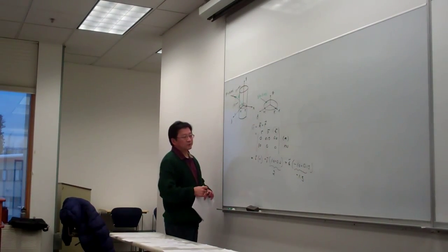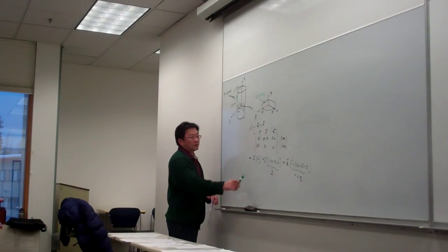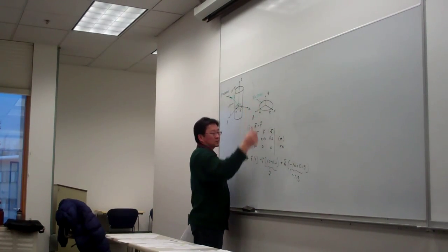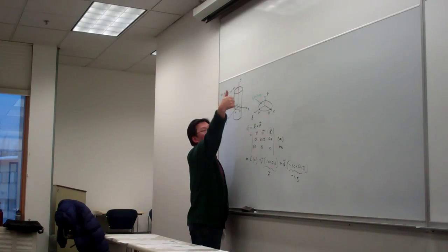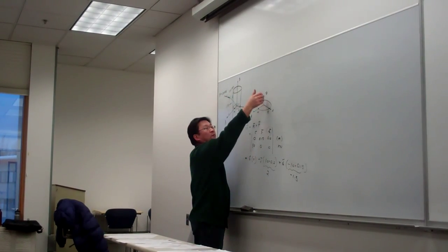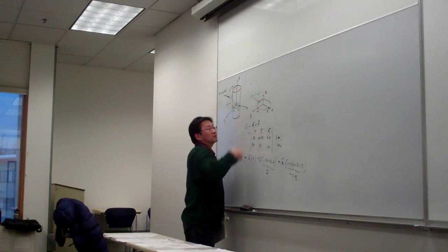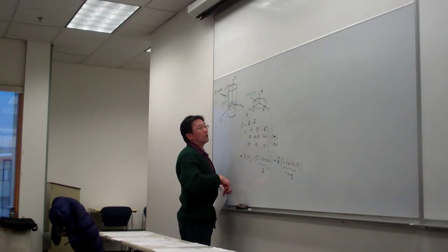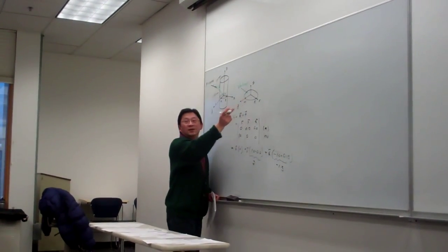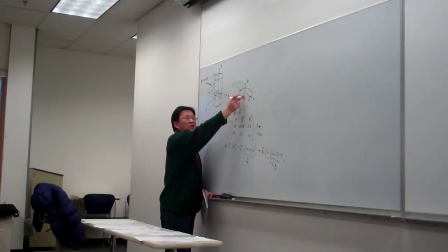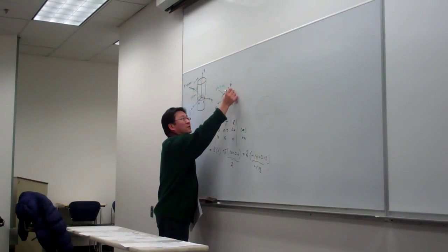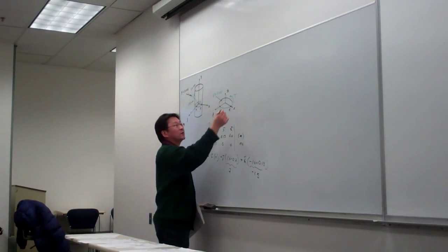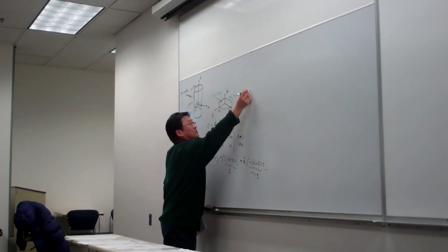So we put this information onto the drawing here. For the j component, the moment about j, which means about the y-axis, is positive 2. Our thumb is aligned to the positive y direction. So positive 2 would be in this circulation. From here, you can see that it is rotating about y. So the moment we calculate here, applied to this problem, is actually a torque. Okay, so here we convert it into the physical meaning. So here it is 2 kilonewton meters.